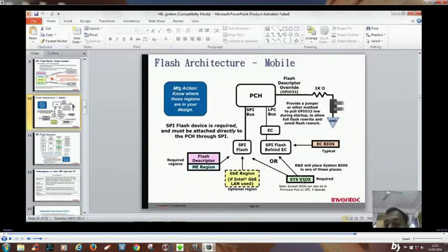But another very important thing is the system BIOS. Where can the system BIOS be? The system BIOS can be in this chip also, and it totally depends on how the company's R&D has been done, and which company is placing the system BIOS where. But normally the system BIOS is put inside the SPI flash which is connected with the PCH.